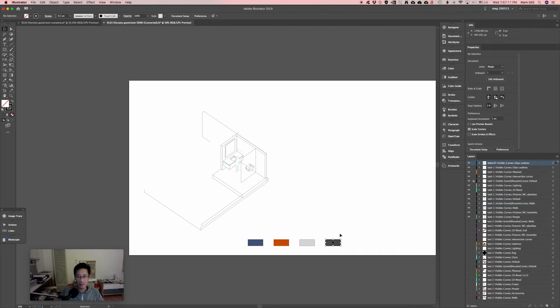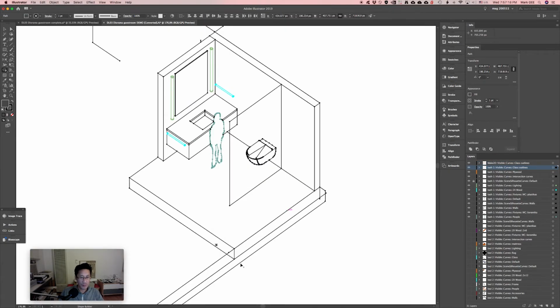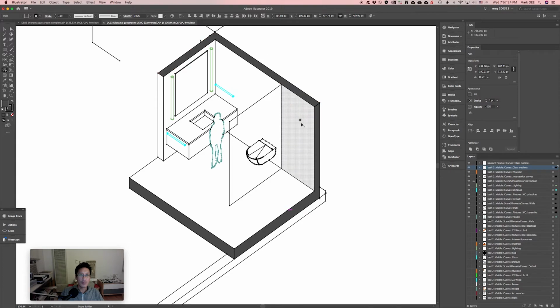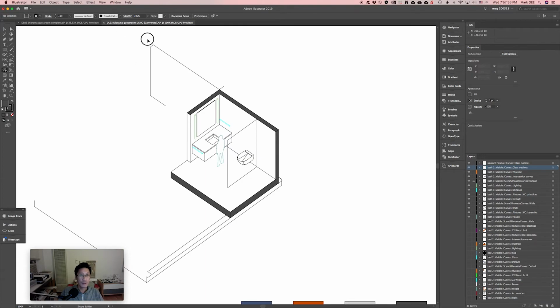So we're ready to do the infilling of the colors. We'll do the same thing. Shapebuilder, after selecting the color, select the objects, use the Shapebuilder tool to find the poché areas. Then we'll switch to the next color, use the Shapebuilder. And we don't need that. We know we don't need that, so we can delete that and clean things up a little bit.